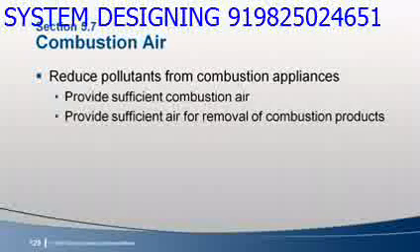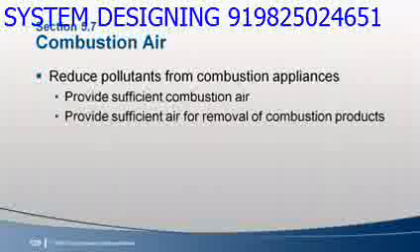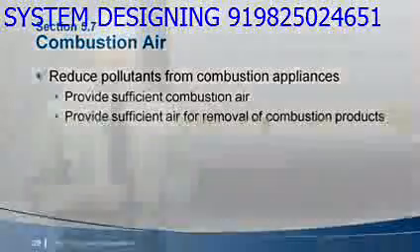Section 5.7 addresses indoor combustion processes. Indoor combustion appliances must have an adequate supply of makeup air to support combustion, and the products of combustion must be removed. That's why gas water heaters need exhaust outlets and gas stove tops need exhaust hoods.